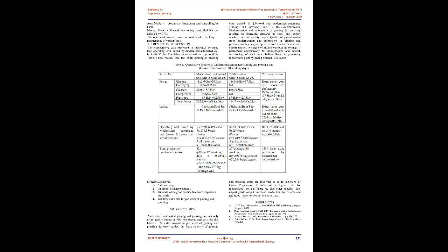4. Selector valves and bypass valves. Pneumatic cylinders are mounted to operate all the valves. Selector valves are located in the pneumatic conveying duct. These valves select the suction points as well as the dropping points for cotton at various stages. Normally there are 4 storage houses. The selector valves select the empty house for loading the ginned cotton being conveyed pneumatically. All these activities are controlled by the PLC.